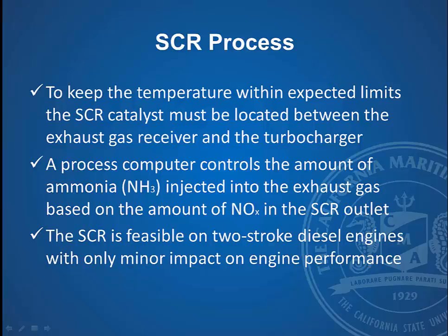And you've got to be careful that you're putting in the right amount of ammonia, because if you inject too much, that ammonia, called slip, will be exhausted out into the environment. So it's controlled by a computer, and it's an exact amount to maintain the NOx at the desired regulatory settings. And depending on what regulatory agencies say about the amount of NOx that you can have, you can just inject more ammonia or less ammonia. And the SCR is feasible on two-stroke diesel engines with only a minor impact on their engine performance.